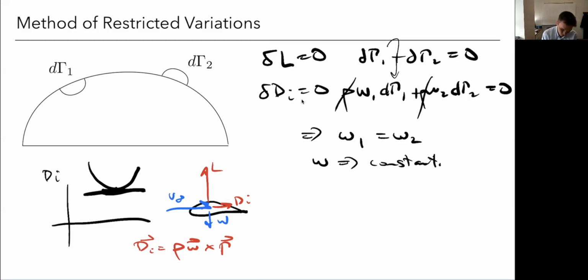So now if I was to draw a top view, here's going towards my wingtip, and here's my winglet on my wing. So it's vertical, and I'm just seeing this airfoil here. Well, the airplane's flying forward, so there's a free stream velocity coming in. And because of this vortex that the wing generates, I get this sideways component. This is just the induced velocity from the wing, right? And so my total relative velocity is now this way, right? It's not just straight on, but because of the sideways component, it's now coming at an angle.